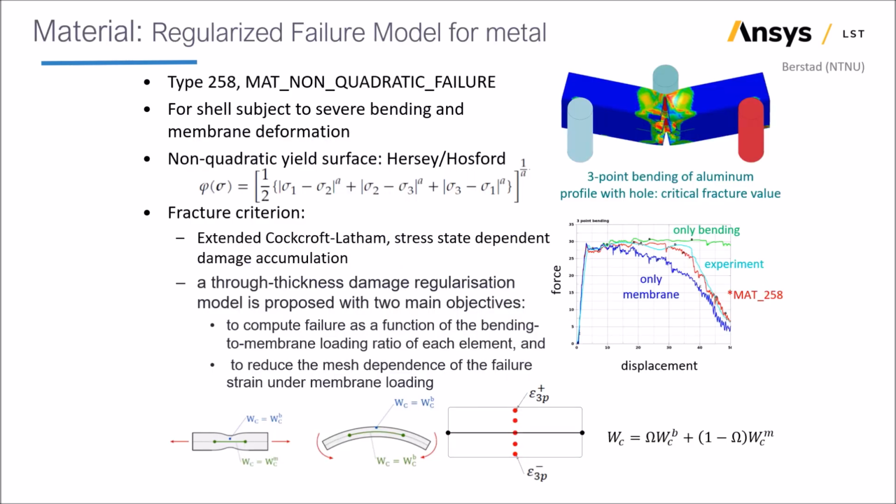This is a new material model focused on damage and failure of metals. It can be calibrated against experiments where the failure properties seem different under pure tension versus bending conditions.